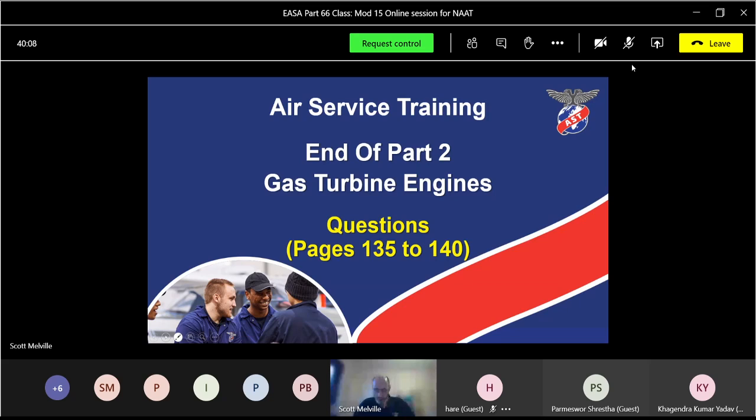Good. All right. Let's pick another good one for you. What would happen if the diaphragm in the governor of the fuel pump failed? There will be a gap. So initially, pressure will keep increasing, because there's a gap. Engine RPM increases initially, yeah.